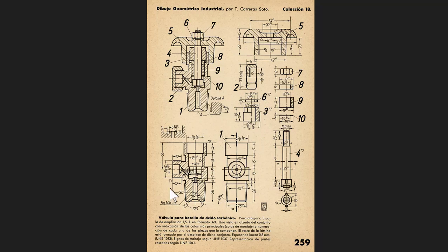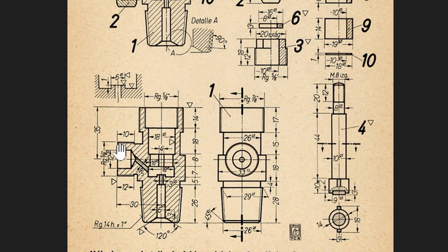This is the assembly, and this is our model. You see, here is 12 and here is 10. I suppose this is okay, but this must be the depth of this hole. We have a conical thread here, which is a British pipe conical thread. We can use the data from Inventor for this. Here is a cut which has dimensions here, or we see how it looks here.